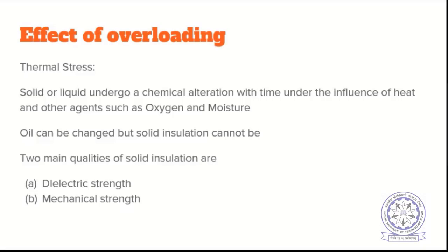But why do we need mechanical strength? The alternating current would also twist and turn the dipoles. Yeah, of course, the winding structure needs to be supported, no doubt about it. But apart from this, even under normal conditions, the current will be there, right? So there will always be a force of attraction or repulsion between the winding turns and then windings.